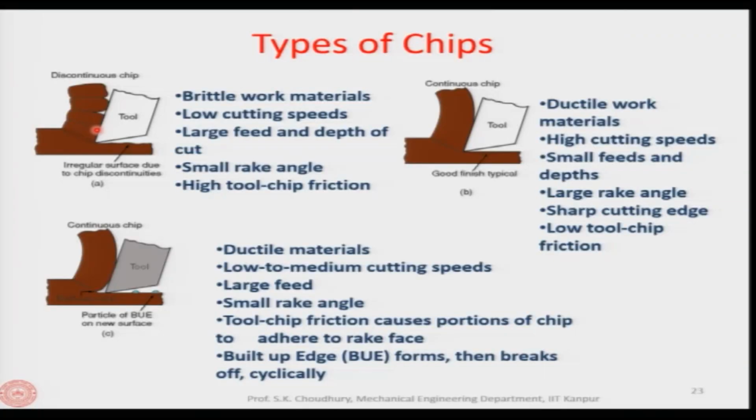In case of brittle material, it cannot go beyond the proportional limit, and it will break. Therefore, the chips formed during machining of brittle materials are discontinuous,